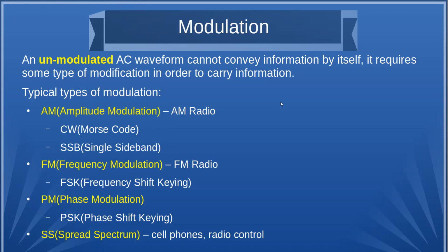One of the basic forms of modulation is amplitude modulation, where we change the amplitude of that carrier signal. Now, you did it by off and on with CW. In normal AM modulation, you're using an audio signal to modulate it, or change the envelope of the carrier wave, which you'll see in a minute.